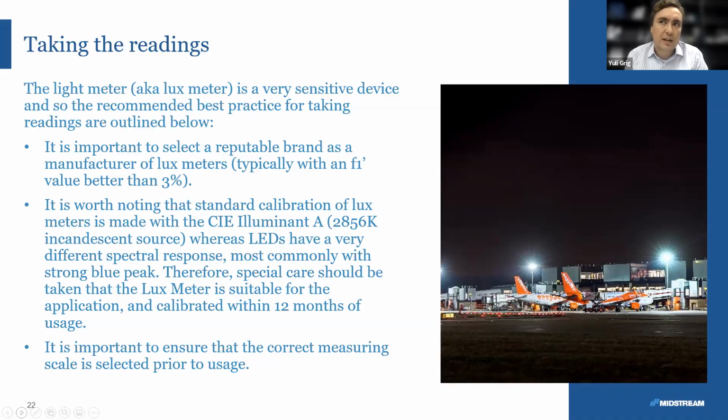Lux meters need to have an F1 value better than 3%. It's worth noting that lux meters should be calibrated regularly. Normally they're calibrated to an incandescent source, to a tungsten, but if you've got LEDs, then let's make sure that it's calibrated to that particular spectrum where you have a much higher peak of blue. And it needs to be calibrated within 12 months. It's also about making sure that we're using the correct scale. We've had instances where people have turned them on and said, well, I'm only getting 2 lux or 0.2 lux, and actually they just needed to change the scale to the correct one.